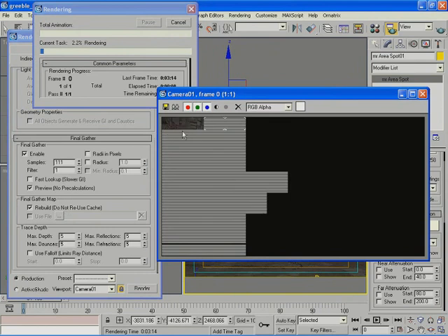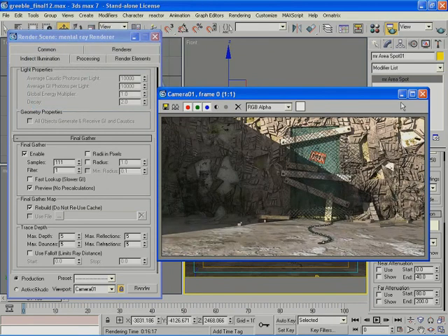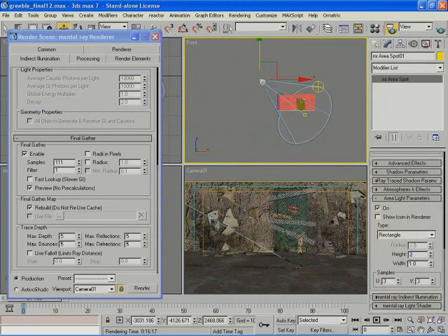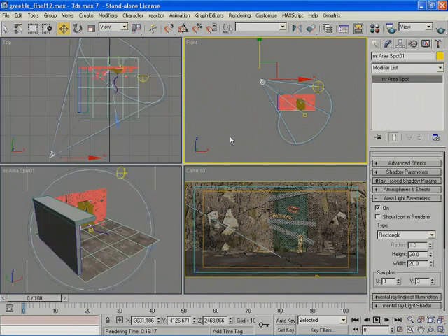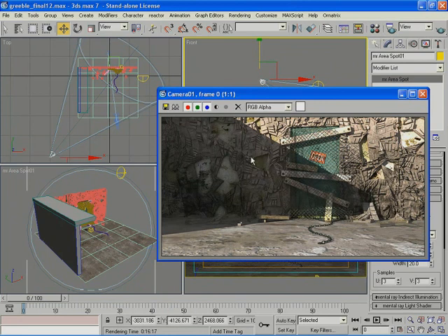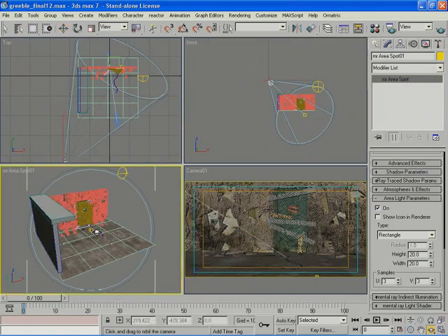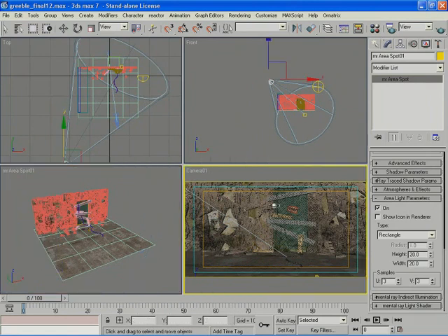The last changes I would do for this image is go down to area light parameters and increase the area light height, say to 20 by 20. And then I would have to, because I want to make this shadow go more towards this part, I would have to turn this a little bit like so. Okay. And the last thing I would do is saturate just a little bit more the skylight color and increase the value to 1.5. That will give me an overall coloration for the shaded area.